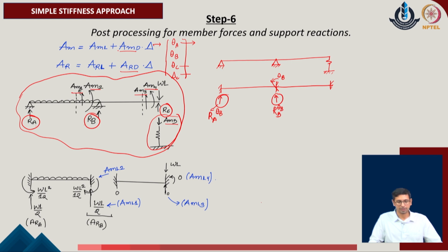In the same manner, one can also evaluate the internal member forces of the given system, and that will be included by a standard matrix which is called A of MD, which is the corresponding member forces with respect to the unit deformations applied in the direction of theta A, theta B, theta C and delta C of the given system, or A of RD, which are the system reactions appearing with respect to all these degrees of freedom of unit magnitude in the given problem.